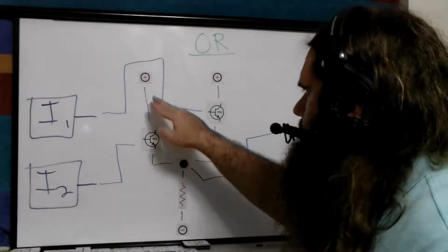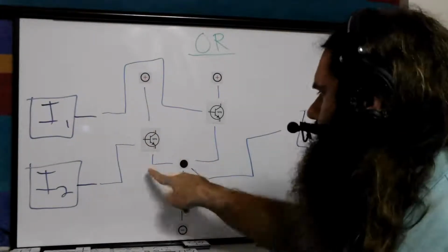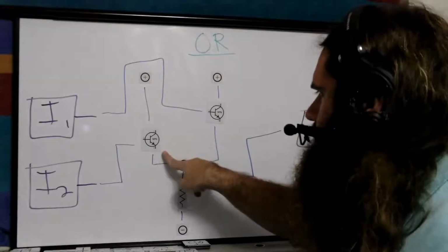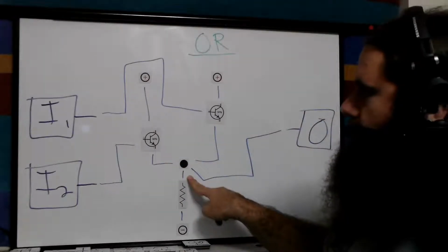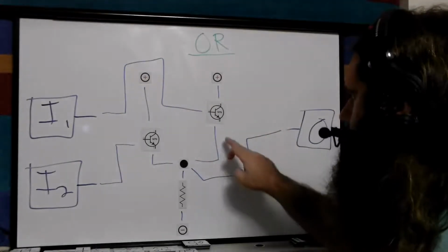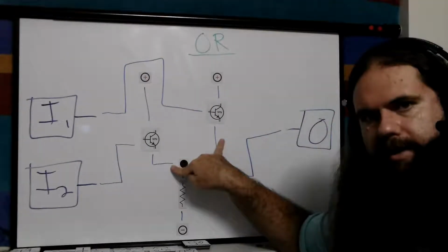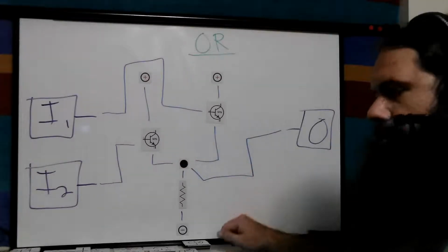Well, we have our loop we already did. This is high, this is low, so it's conducting. 5 volts, 4.8, 0, so 4.8 here, but is it consistent with the other one? Well, yes, because we do that and we get 4.8 here, so 4.8 at the end of both transistors. So there's our OR gate.